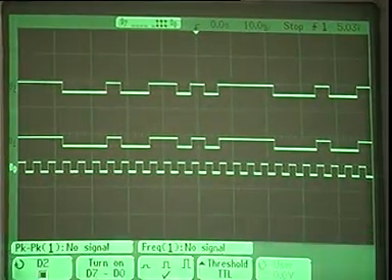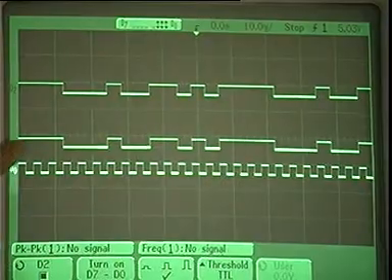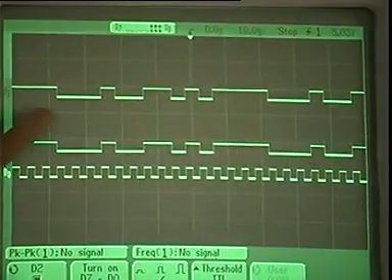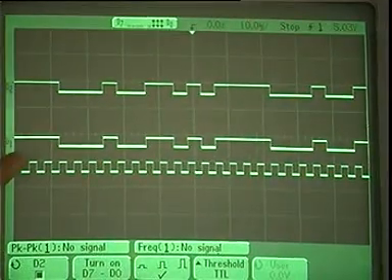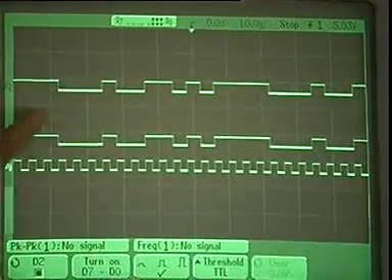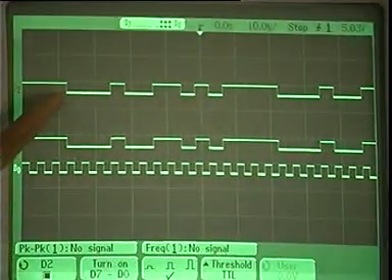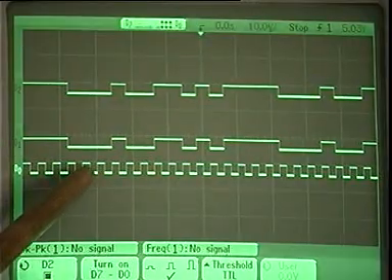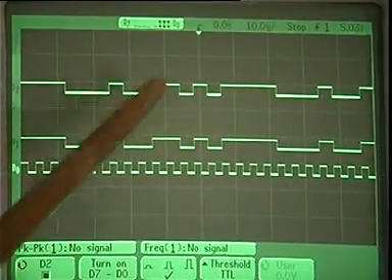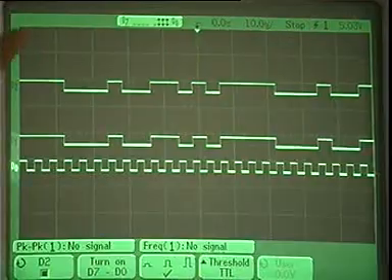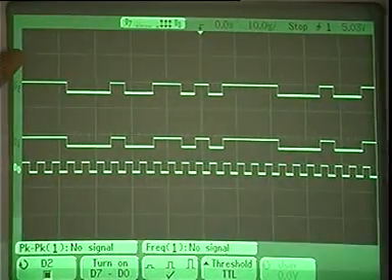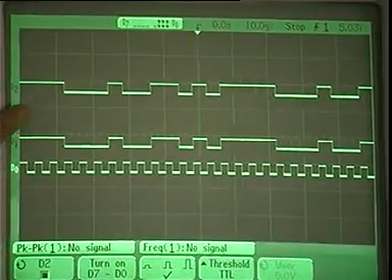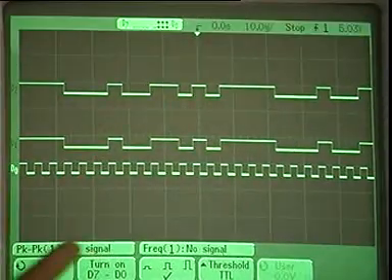So what could be the data here? Each clock period corresponds to data being 1. So this is 1, 1, 1. There are 3 ones in this. This rectangular waveform, the middle one, stretches to 3 clock periods. So there are 3 ones followed by maybe 3 zeros. There is a single one, there are 2 zeros, and so on. This is the corresponding NRZL waveform. The NRZL waveform will look exactly similar to the data. This is the way I transmit the NRZL waveform.